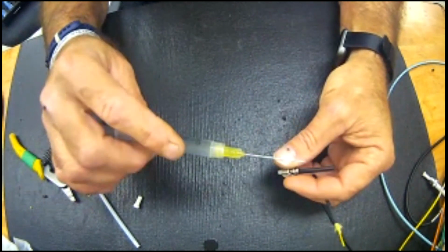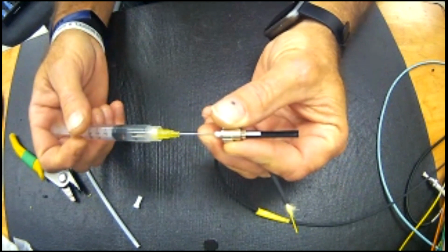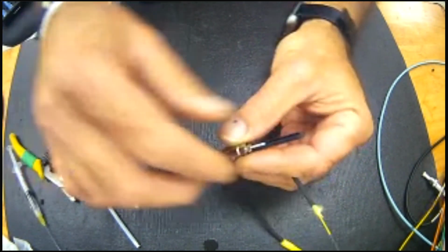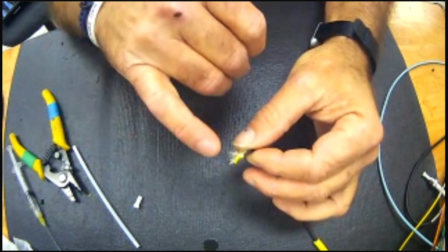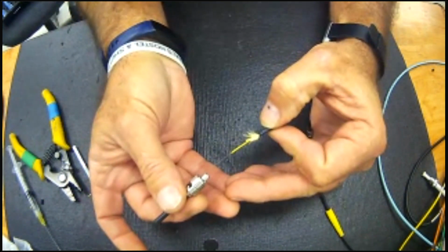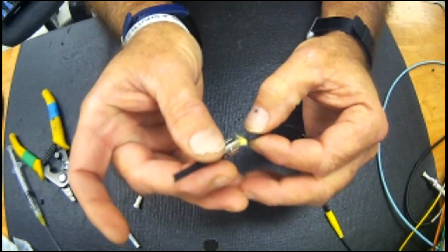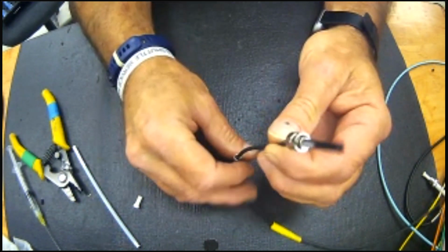But I put a little bit of alcohol in here to simulate the epoxy. So we would squirt a little bit of the epoxy up inside the connector, flare out the yarn because it's basically mimicking BNC or braid, and then I'm going to slowly work the glass up through the connector like so.